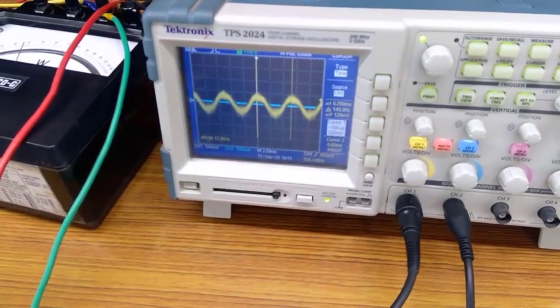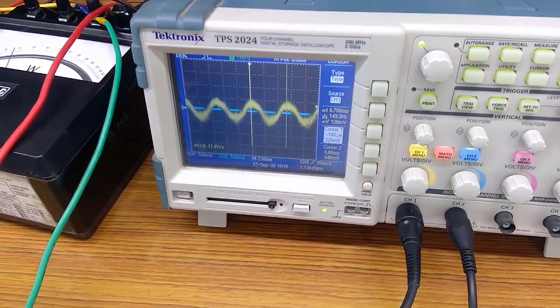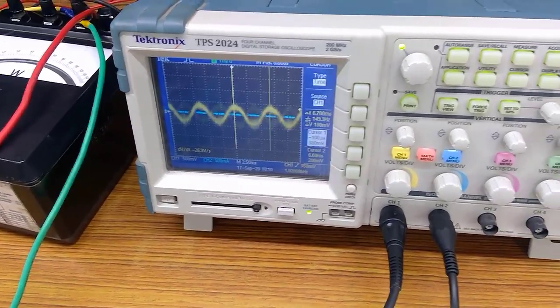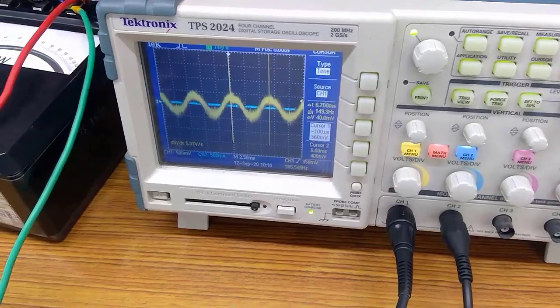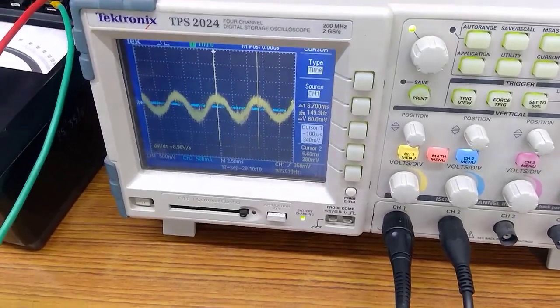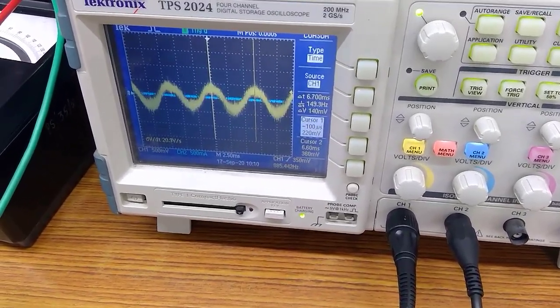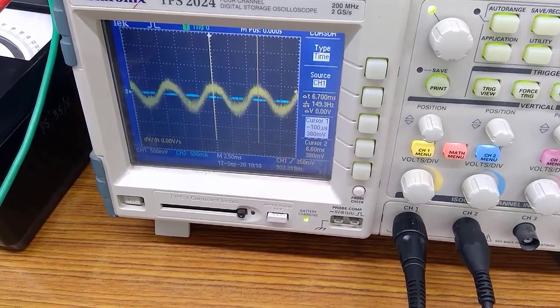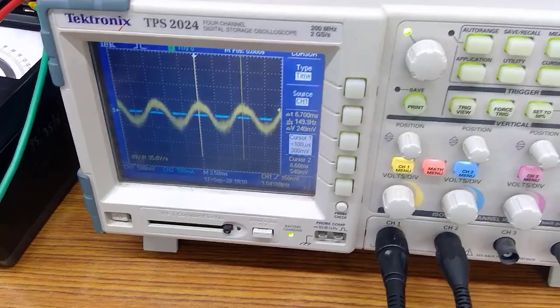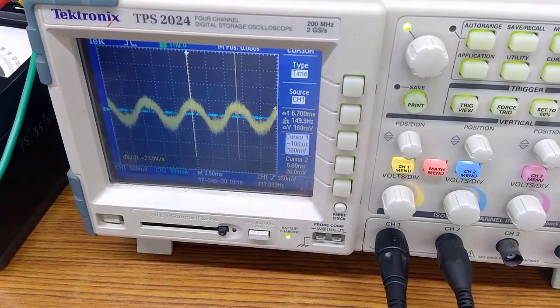But if you observe here, we have already energized it, and this is the voltage: the yellow one is the voltage waveform and the blue one is the current waveform. The current is almost 0, means it is 0 only, and you just focus on the frequency component there, the cursor point. These two cursors, if you see the difference between them, the frequency is coming around 149.3 Hz.